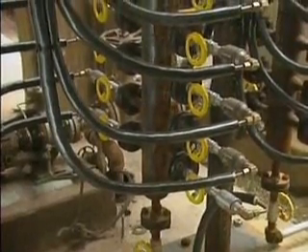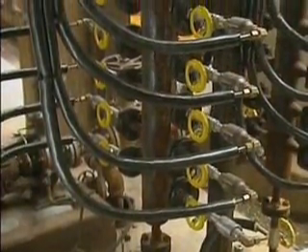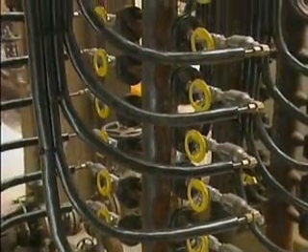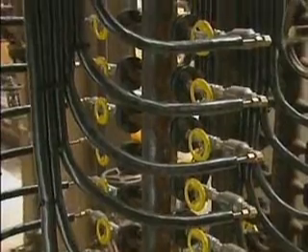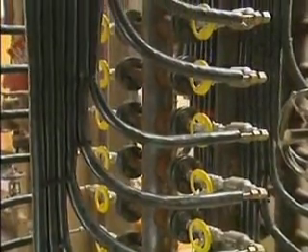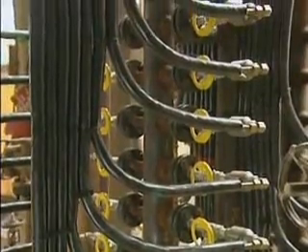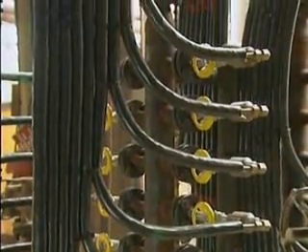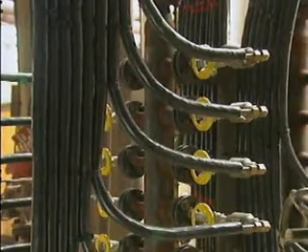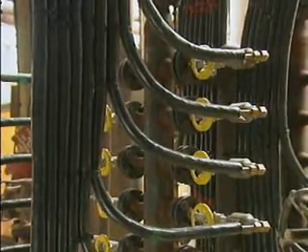For instance, if a series of traps are installed on a manifold setup so they discharge to a single return line, back pressure may rise because of faulty traps. But the back pressure will rise on all the traps in the system, good and bad alike. So a temperature inspection alone probably won't give reliable information about the condition of a specific trap.